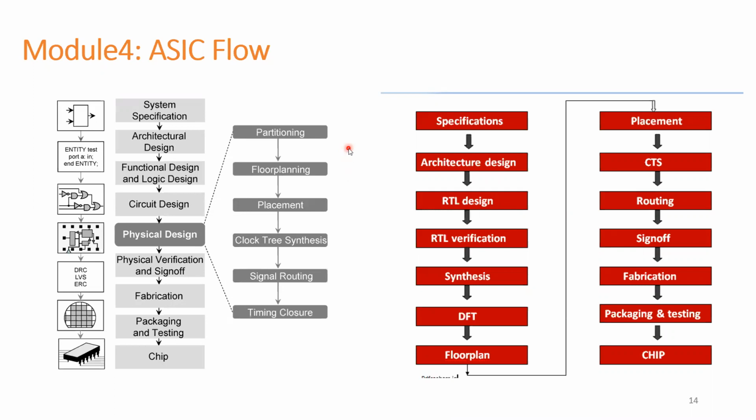power planning. So in power planning, we will create the PG stripes. PG means power ground stripes will be created to provide the supply to all the standard cell logic that is sitting in the core. If you do hands-on project execution, you will get to know, you will get the clear picture.